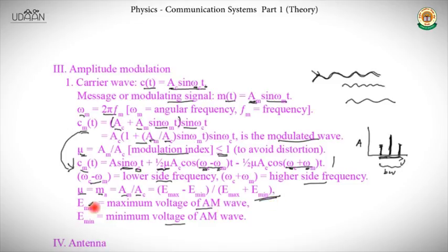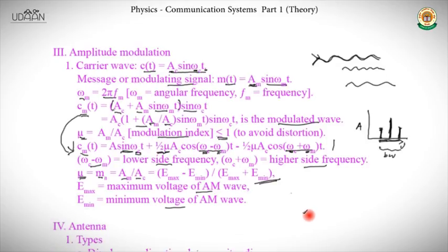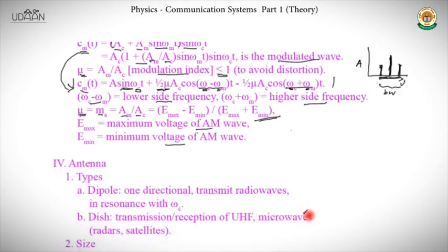would give us mu. So this is shown because when you represent amplitudes in terms of voltages, there is usually no zero voltage transmitted. There's always a minimum and a maximum voltage transmitted. So when you write that expression in terms of AM and AC, this is what you arrive at. So we get the modulation index in terms of voltages of the wave, which can be related to the voltage of the transmitter itself. So that we can get these voltages fairly easily. So that will give us the modulation index.